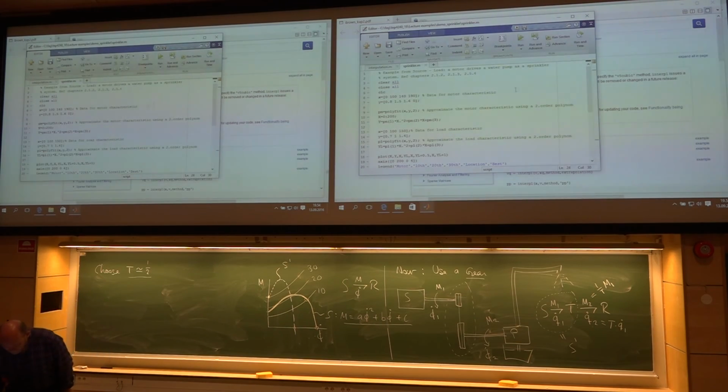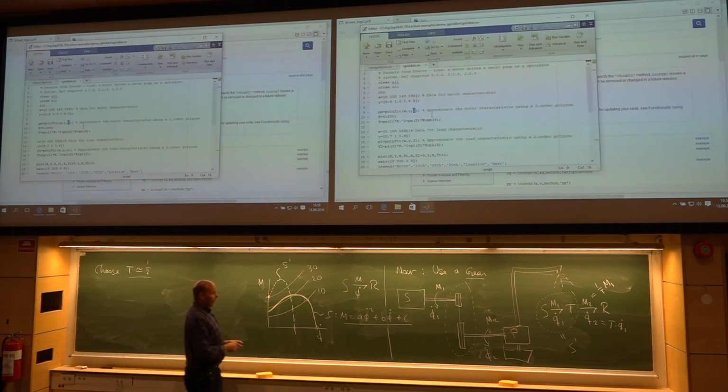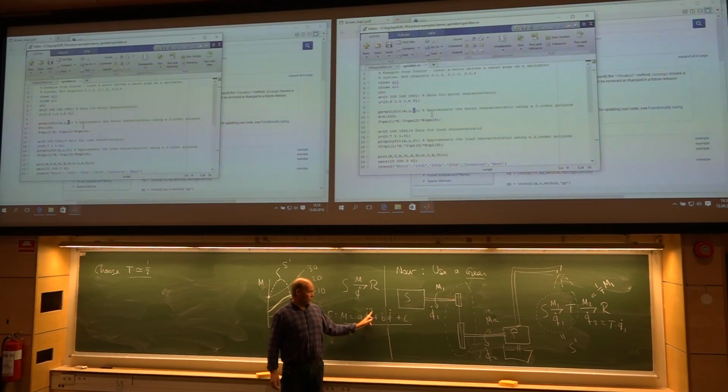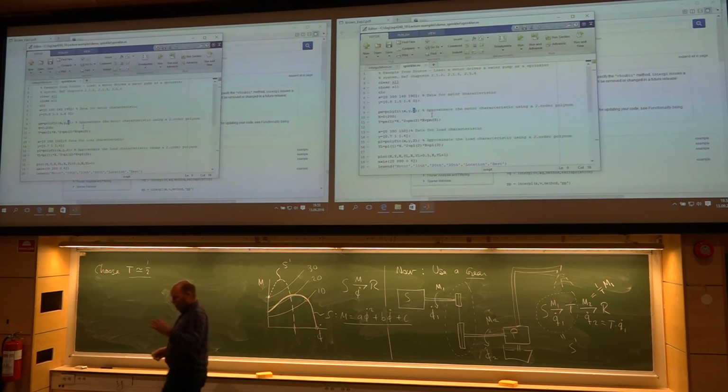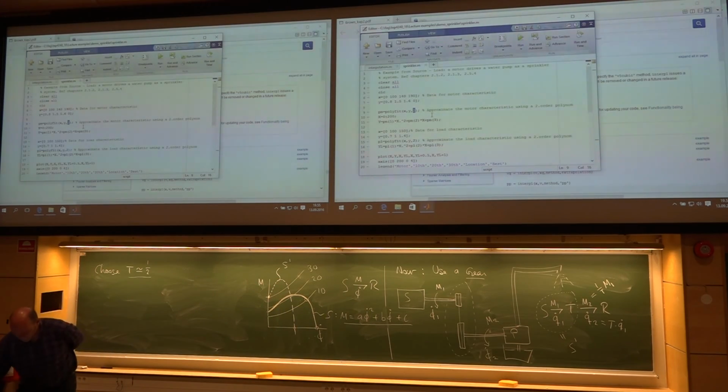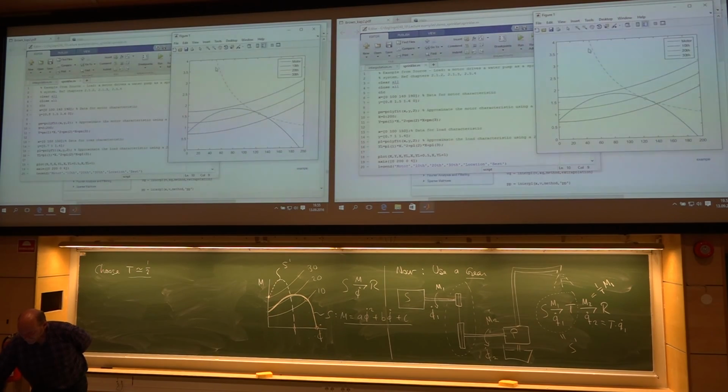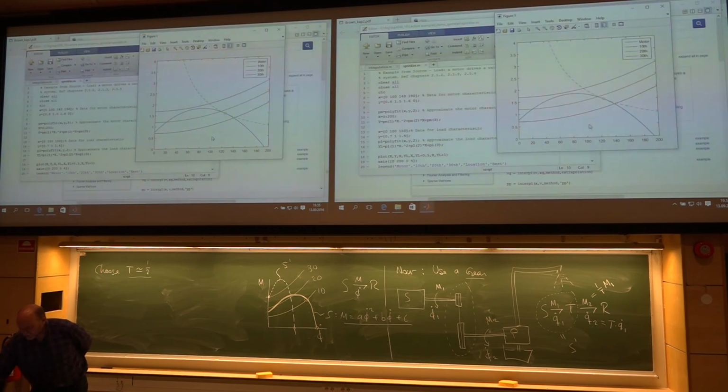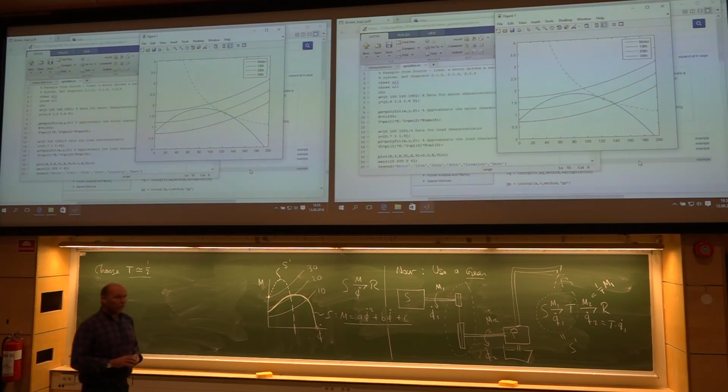And yes, that can be done with polyfit. You just give him the original data and then specify the order of the polynomial you want to use. Here, second order is a fairly simple curve, so you shouldn't have any problems with that one. And then you can actually play around with such problems fairly easily.